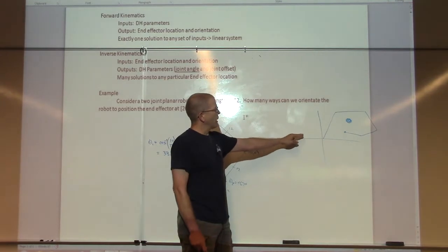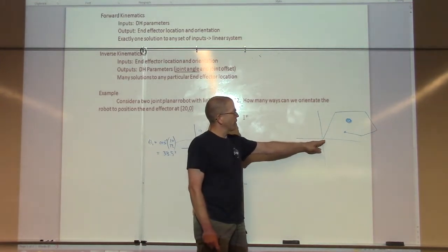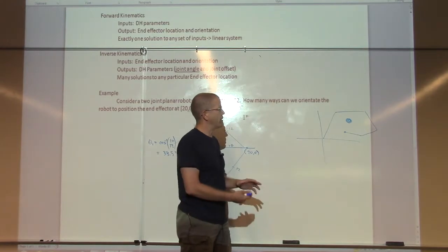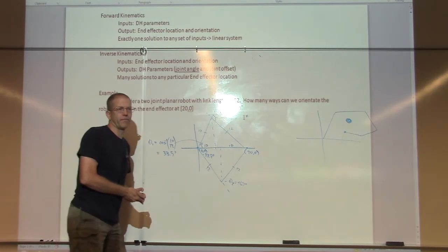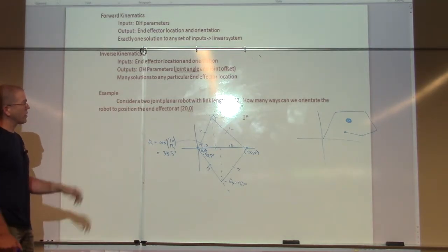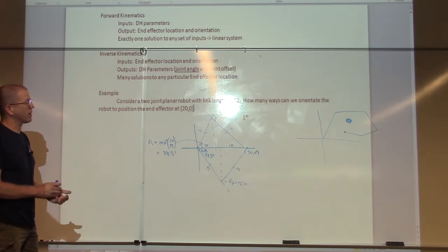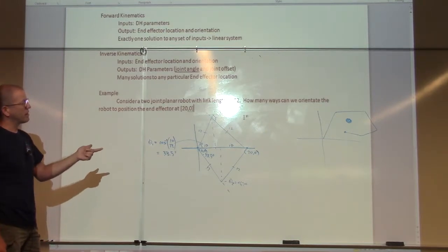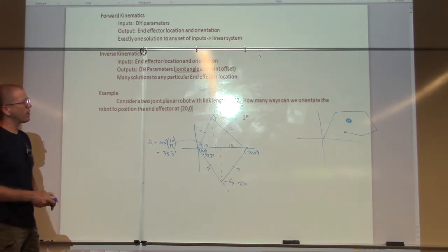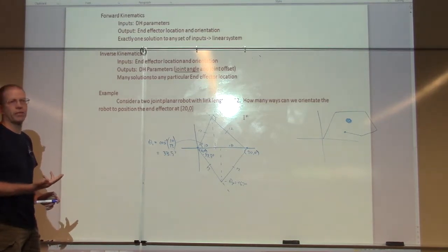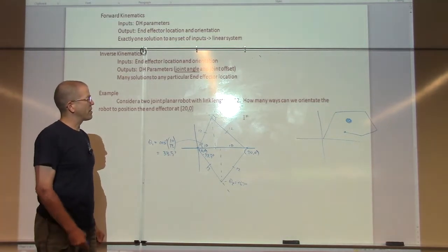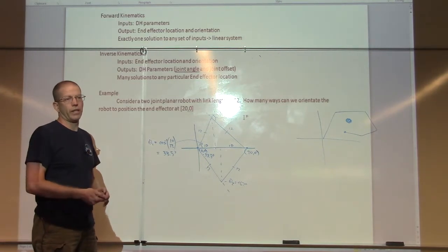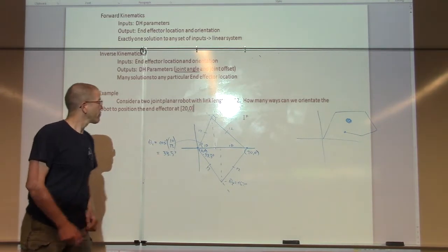So when we're dealing with a robot with redundancy built in, that redundancy can be used to navigate around obstructions within the workspace, okay? And so when we begin this week's assignment, keep in mind that even though we typically only need 3 degrees of freedom to position and orientate in the plane, we oftentimes have a certain amount of redundancy built in just to avoid obstacles, okay?